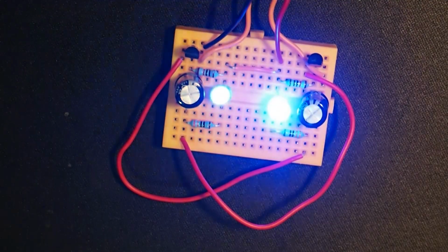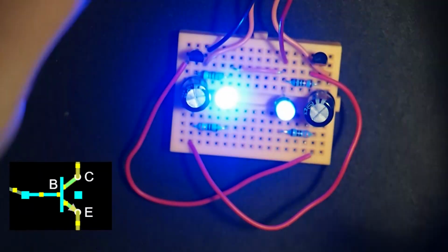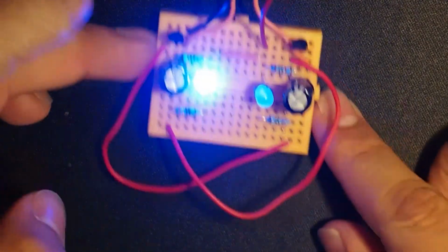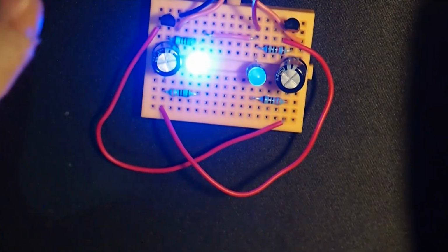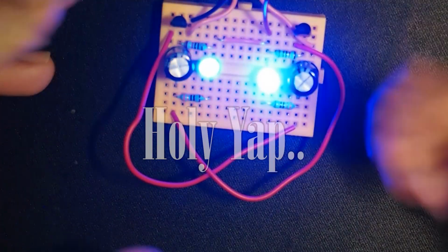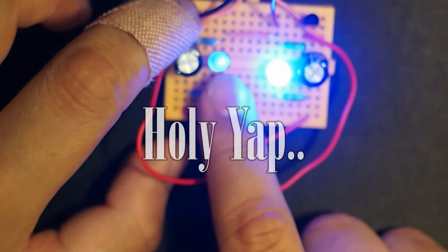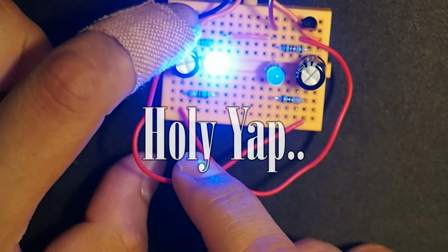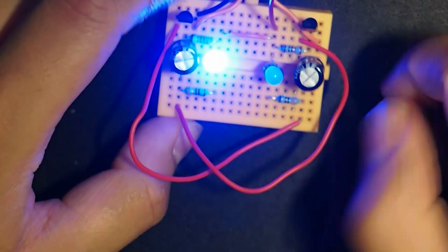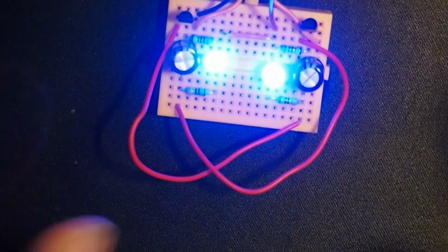Alrighty, so what I had done incorrectly before is I had connected the negative terminal to the collector and not the emitter. Basically nothing was happening, but yeah, I mean, this is it. So this is working exactly like the simulation. The capacitor slowly charges, the LED needs to turn on, and once the capacitor is fully charged up, this LED turns off, right? And the cycle then continues, and then as soon as this transistor turns on, current is allowed to flow through this capacitor, which slowly kills the signal in here. Yeah, that still didn't really make any sense. So hopefully one day I'll be able to explain it properly.